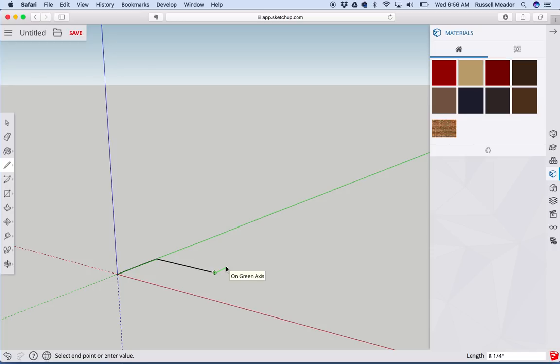Now that I've got those 2 dimensions in, like I said earlier, everything is going to default all of your angles to a 90-degree angle. So when I start to kick back down towards the red axis, all I'm waiting for is for the little controls to kick in, and I don't know if you can see that, it's automatically going to kick it to the green axis.